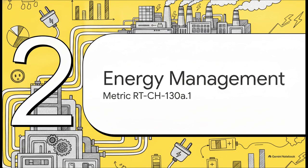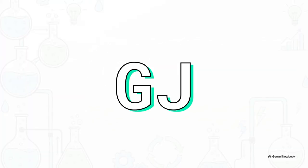Section 2. Energy management metrics. When we're tracking total energy consumed, that big aggregate number absolutely must be reported in gigajoules. This is going to include your purchased grid electricity, direct fuel usage, heating, cooling, steam, and any self-generated power. But watch out, because there's a really strict mathematical rule here. When you calculate energy from fuels, you have to use higher heating values. Basically, that means you're measuring the absolute maximum gross heat energy released during combustion, and you've got to use baseline data from the IPCC to do it.